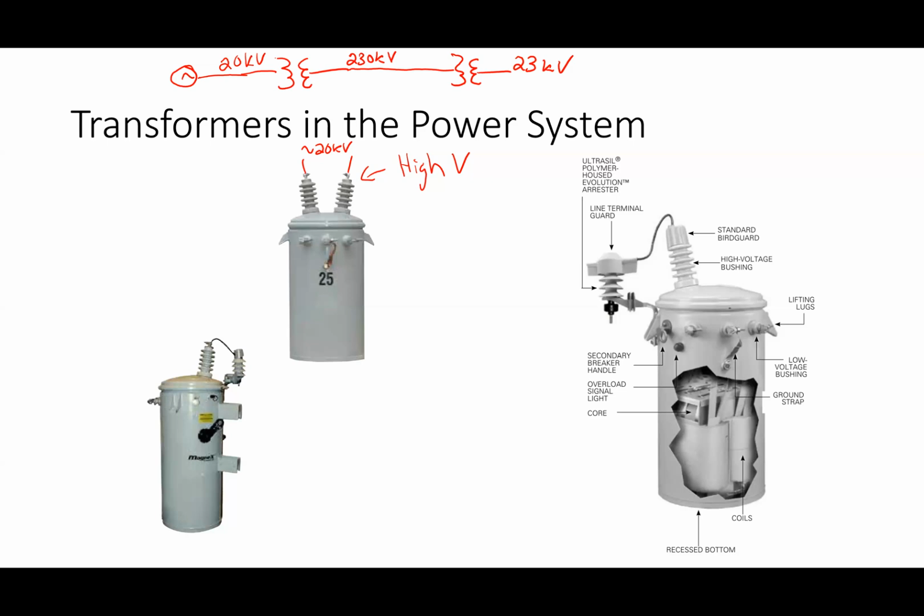So 23 kV is when you're driving down the road and you're watching those wires overhead, it's going to be 23 kV probably going into these high voltage taps, we call them. And then on the low voltage taps over here, we'll have 240 volts coming out if it's going into a house. All right. So first of all, if I have all these, let's think about over here. Here's your house at 240 volts.